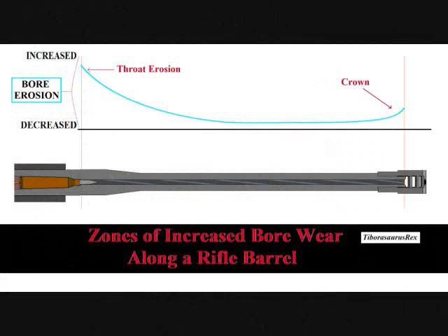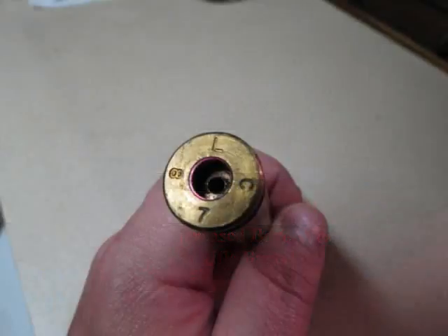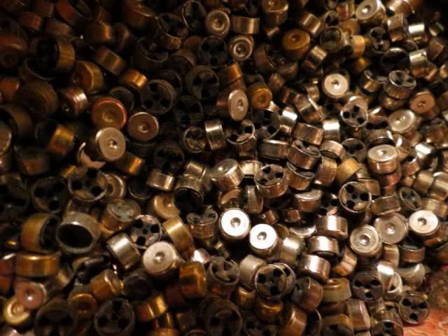And one thing we have to take into consideration here, though, is that most of the literature we're going to find talking about bore wear, and even most of the new literature, is going to be citing the old literature about propellant residue, gunpowder fouling. And the old literature is based on old chemistry, which is the original powder recipes. Even when I'm talking about propellant residue, that includes your primer chemistry as well. That's not just the propellant, but the primers specifically, back in the old days, up until World War II and even after World War II, were quite corrosive, mercury fulminate-based primers.